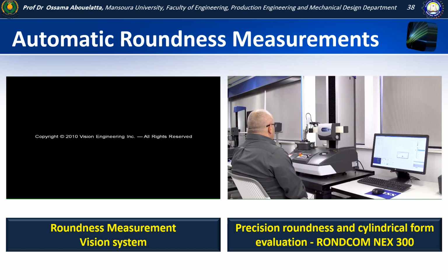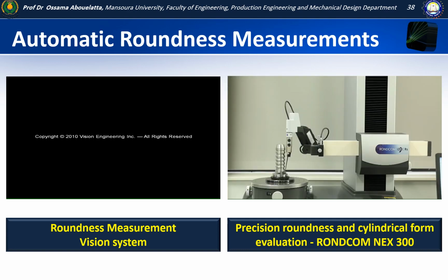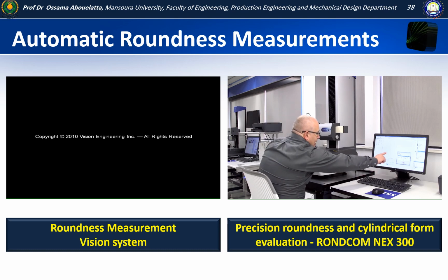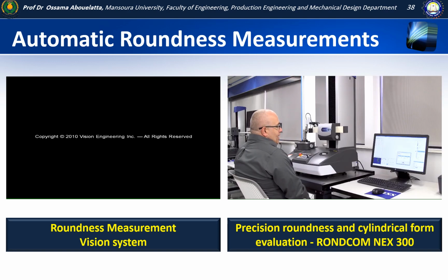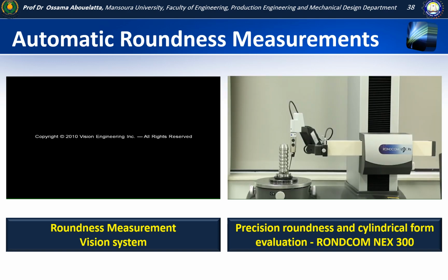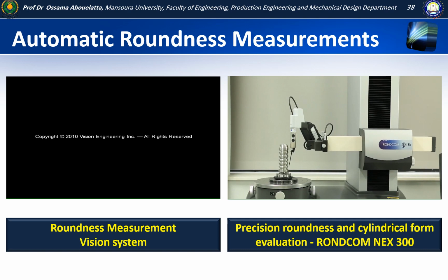The first thing that we will do here is we will pick a point at the lower extremity of the workpiece and one towards the top of the workpiece. As you can see on the screen here, we have an alignment box. From here we are able to choose the amount of eccentricity as a target for the alignment, so we're able to fine-tune the amount of alignment that we want.